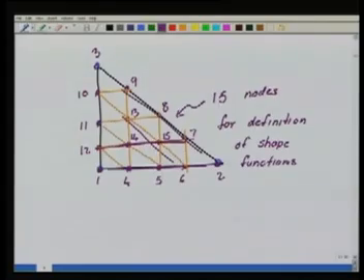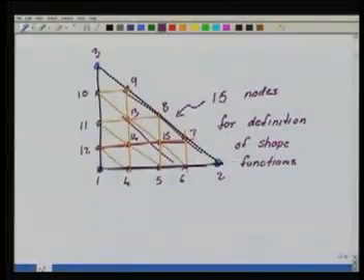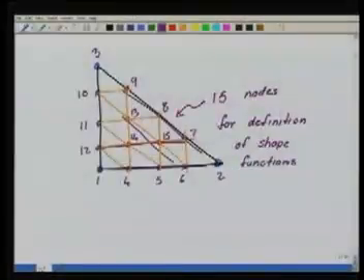Okay, so I can keep on constructing the higher order approximations to any order that I wish by using this kind of a structure, and it is quite easy. It can be done in the master element and immediately used. Okay, so in principle now we are in a position to construct any triangular Lagrangian basis function of any order that we wish to obtain. And the beauty of these basis functions is that you have exactly the number of functions that you need to have a complete definition of the polynomial of the given order.